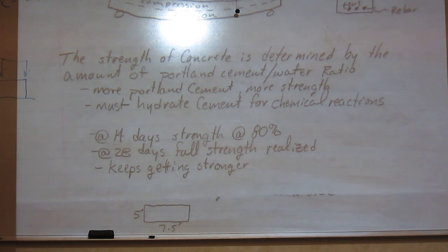That is the weak part. That is the cement. The aggregate you put in there is much stronger than that. The rock we add to this stuff is upwards of 40,000, 50,000 PSI. So here's what concrete companies are held to when you order stuff. Many of you might get into this as a drafter. A lot of times we're taking these concrete samples. We're out on the trucks when they're pouring bridges and taking these and testing them.